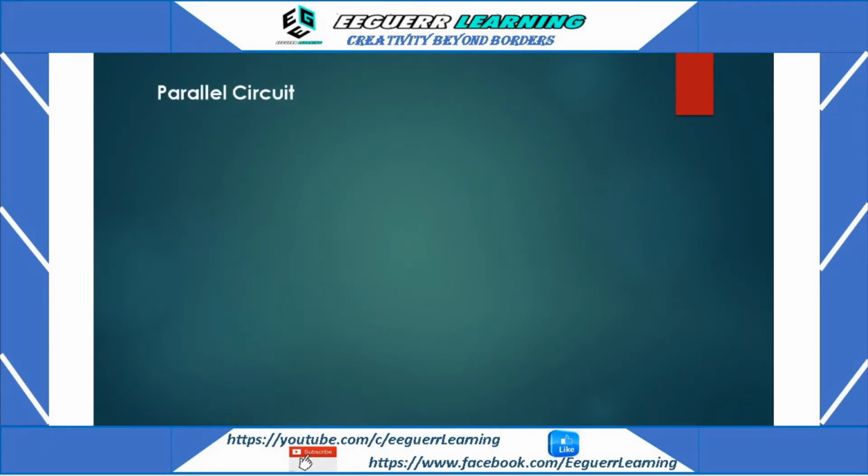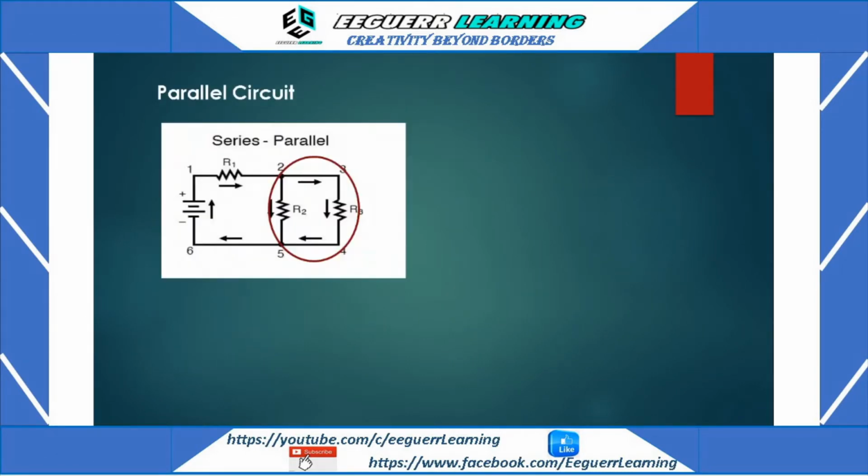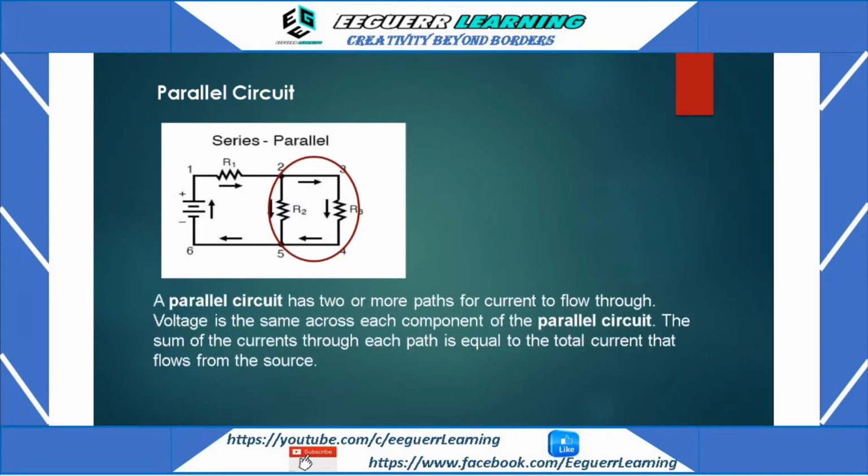With the parallel circuit, let us define what a parallel circuit is. A parallel circuit has two or more paths for current to flow through. Voltage is the same across each component of the parallel circuit, and the sum of the currents through each path is equal to the total current that flows from the source.